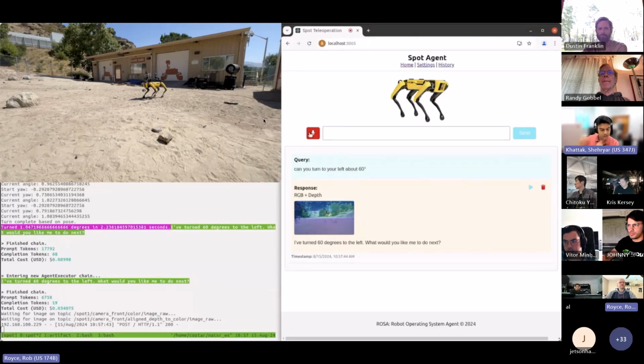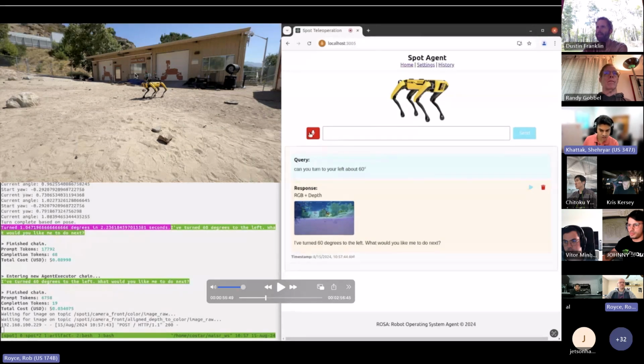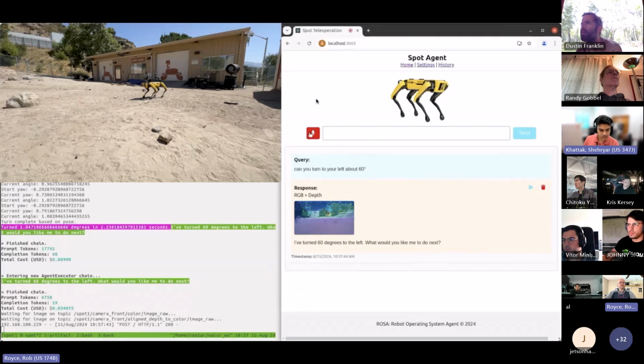No, we just use the API, so the robot is as it is. You see the body, but the black box and all the sensing that you see is all done by JPL. So there's the LiDAR, the IMU on top, the thermal camera, the RGBD camera. There's an Intel NUC inside in the black box. There is also a Jetson AGX Orin, a 64 gigabyte model in there. Then we have our own comms network on top. So as it moves around, it can actually lay down comms. So it's like a backbone. If, for example, we're going inside a cave or something, because hopefully one day we will find life there in a cave somewhere.